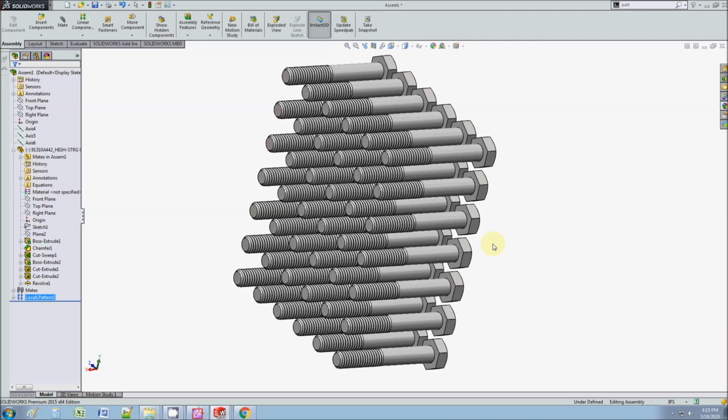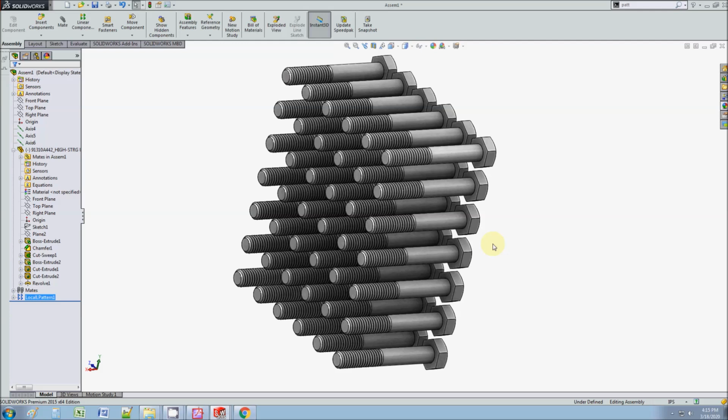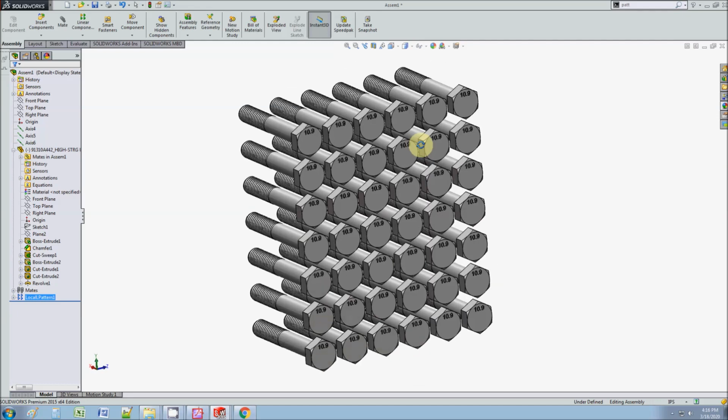One thing I would caution is sometimes when I've used this, it tends to glitch out a little bit on updating drawings as far as configurations are concerned. So sometimes when I've had to update configurations using the pattern tool, I've noticed that it glitches out. It doesn't update properly. So just be aware of that. Sometimes you have to hit refresh. You can still get it to work, but it's going to be a little bit glitchy when you work with slightly complicated models and assemblies. You might come across problems. So there's a pro and con to using this tool set. But that concludes the patterns, okay?